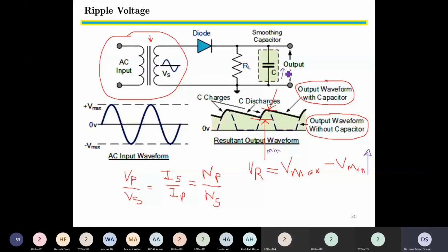So although large or very large capacitors help in decreasing the voltage ripple, at the same time we are left with an uncontrollable circuit. Uncontrollable in the sense that if we switch off, the device will remain active until the capacitor loses all its charge. Is this understood by everyone?